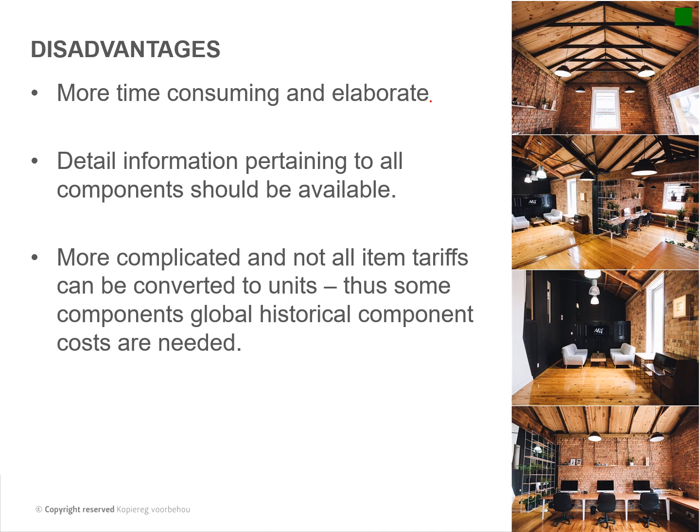Thus, for some components, global historical component costs are needed. So you need accurate information to actually build up these rates. But what is nice about this is you can actually get new rates. For instance, you can go to builders and get the cost of a toilet, and add your installation cost, add your profit, and so on.